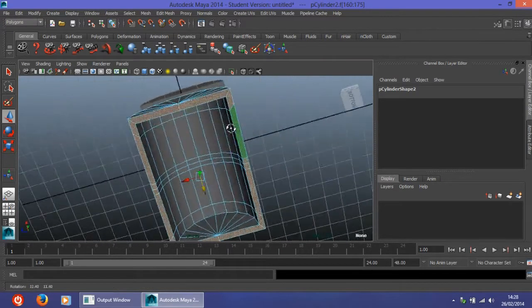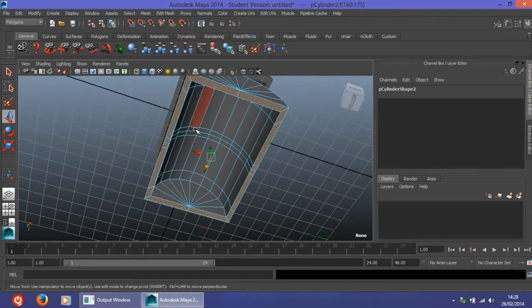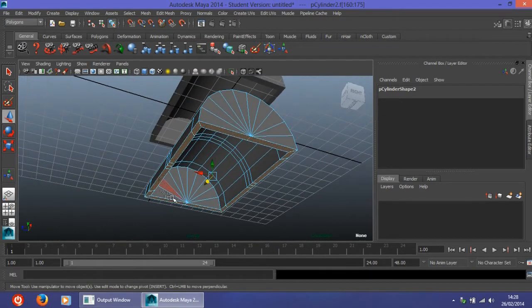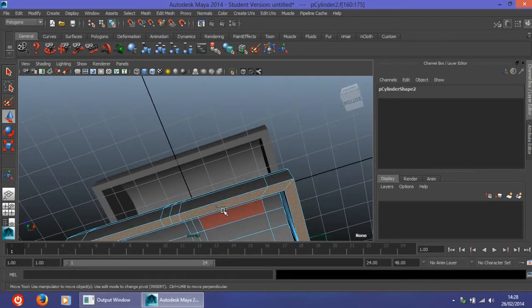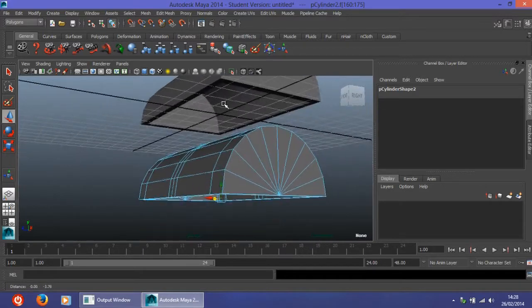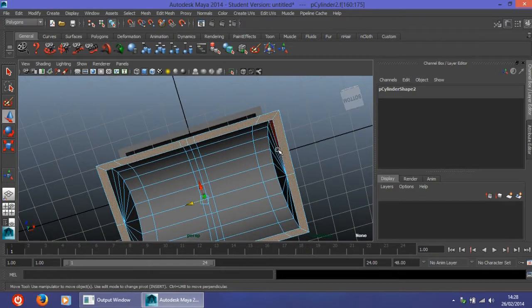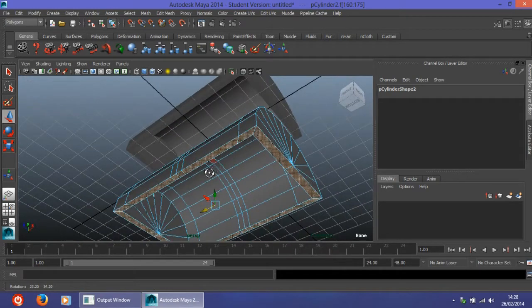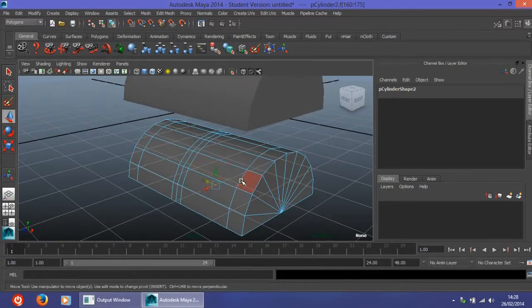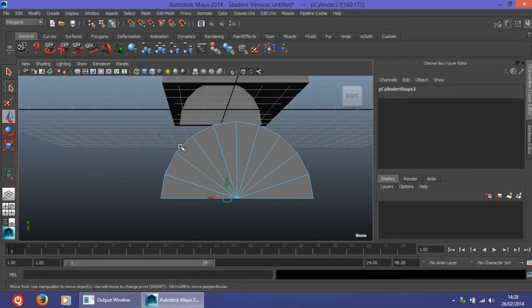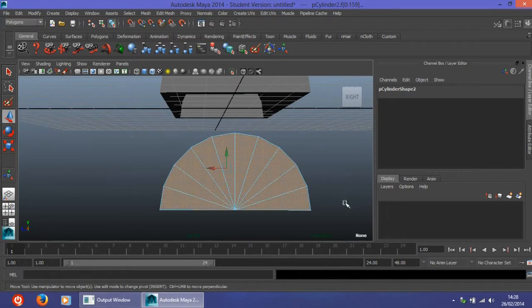So to show you, we need to delete all the faces except for those 4. That's because we need the same thickness that we made on the lid. And if we do the same thing with a square or something like that, we don't achieve the exact same width. Therefore, we need to have those faces ready to be exactly like the other one. So just select the other faces by dragging right there.